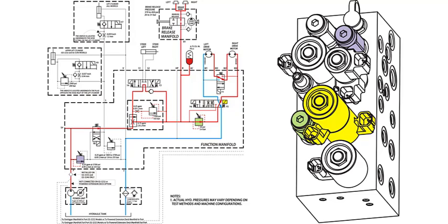As the drive joystick is released, the drive solenoid is de-energized and the electric motor shuts off. The drive valve is allowed to return to the spring-centered position. The machine is no longer being propelled by the hydraulic system. Its momentum forces the motors to continue to spin, in turn, forcing them to displace oil. The ports in the center position of the drive valve restrict the oil being displaced, as depicted by the orifice symbols, causing the drive motors to slow and act as service brakes.